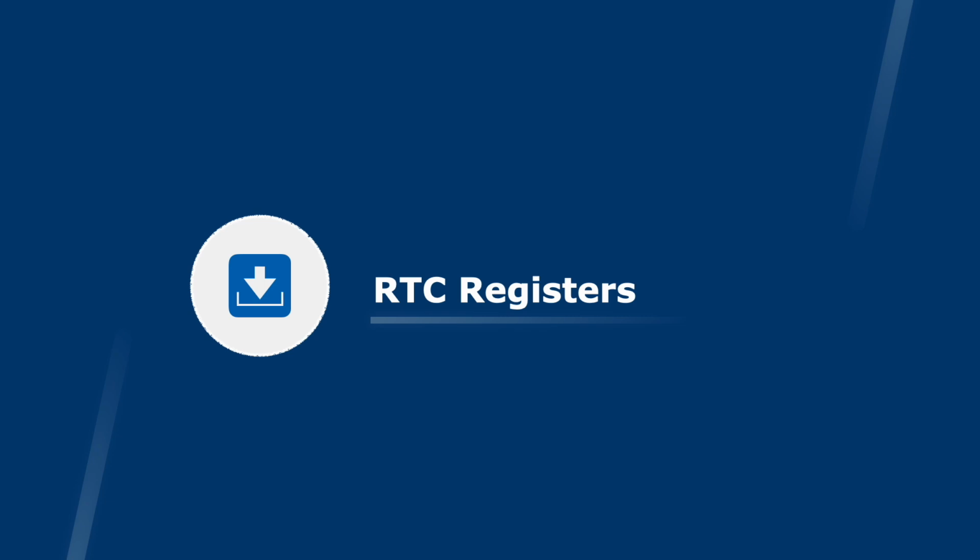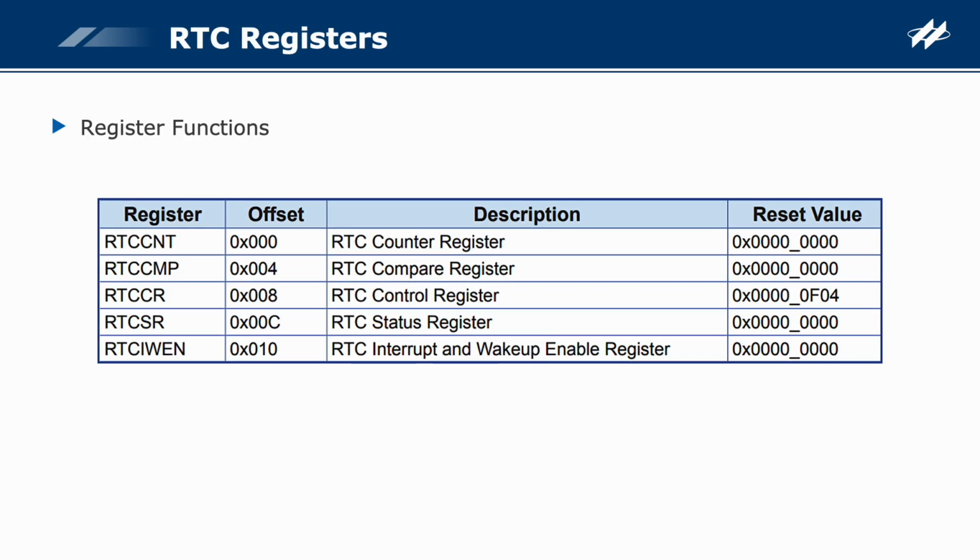The second section is about RTC registers. Then, we'll briefly introduce the RTC-related registers. The RTC counter register is used to store the RTC time count value. The RTC compare register is used to store the specific value to be compared with the RTC CNT register. The RTC control register defines various RTC circuitry control bits. The RTC status register stores various RTC flags.